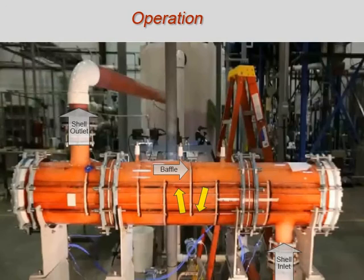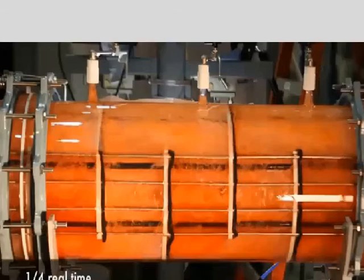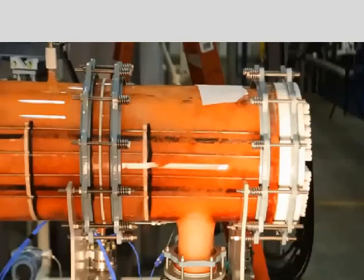This is a shell side of a shell and tube heat exchanger. You can see the baffles along the flow path from the inlet to the outlet. The flow is entering the shell side from the inlet on the bottom of the shell and exiting through the outlet on the top. You can see the change in direction through the length of the shell as the liquid flows around the baffles, causing the liquid to go across the tubes multiple times.